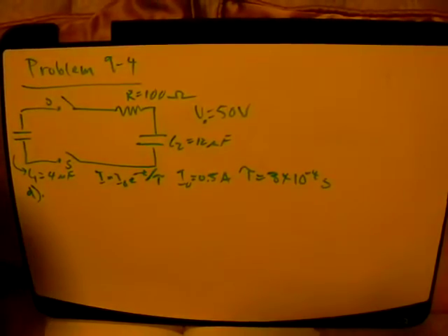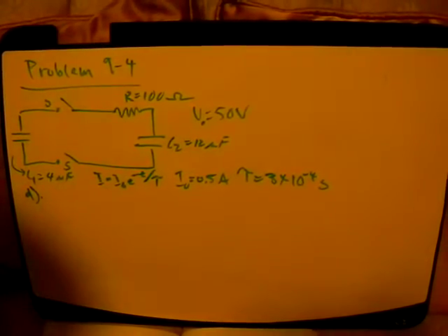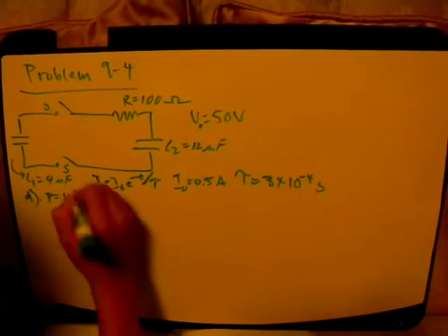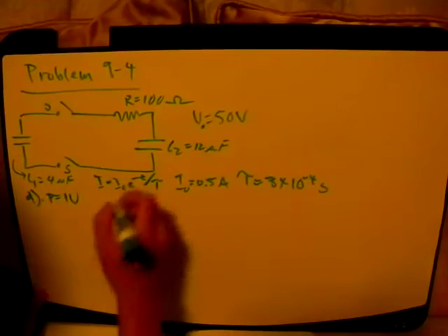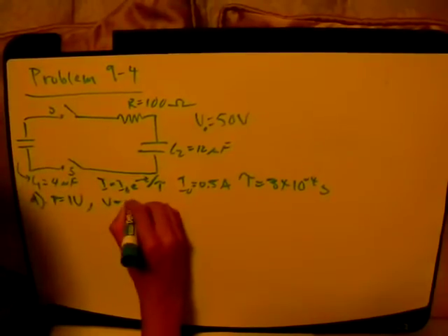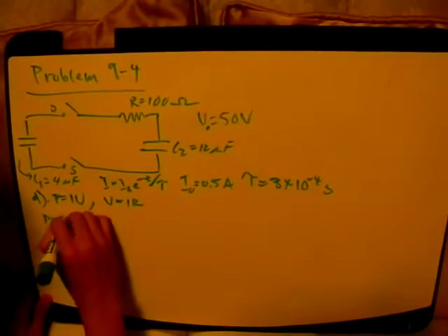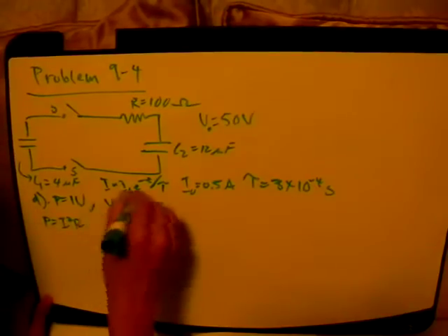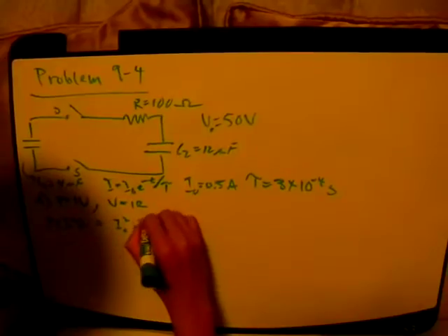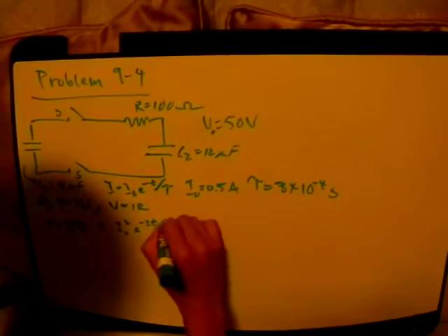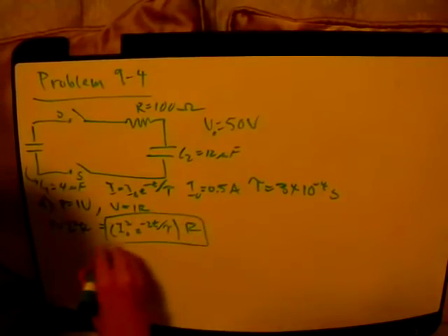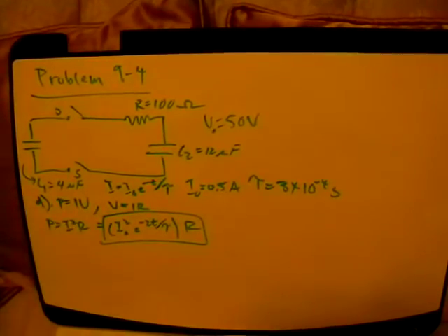Determine the rate of energy dissipation in the resistor, also known as power. So we need to find power, which is equal to IV, in terms of time. We are given I, but we don't have voltage. But from Ohm's law, V equals IR. So we can plug that in, and we get P equals I squared R. Plugging this in gives I naught squared R e to the negative 2t over tau, because exponents multiply. That's power. And notice, it is in terms of time. We have t right there. So that's D.